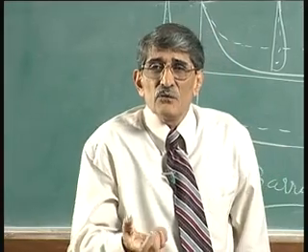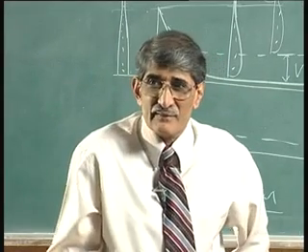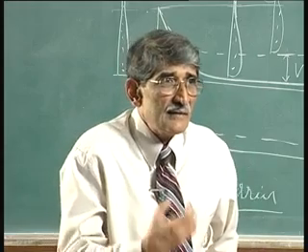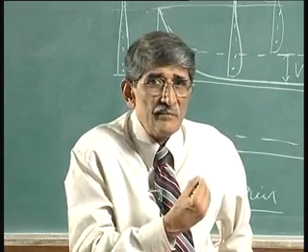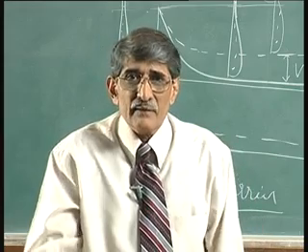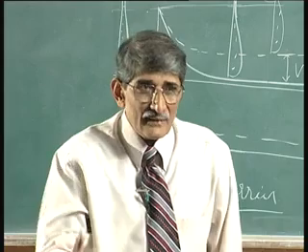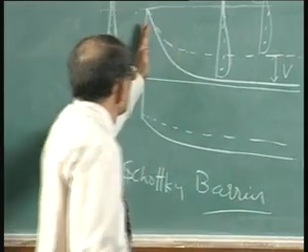So you have that number much smaller than the equilibrium concentration. If you have 10 to the power 16 as the equilibrium concentration, the crossing number is much smaller, maybe 10 to the 11, 10 to the 10. So, it is like putting a drop of water into the ocean, it disappears immediately. In the sense, it is not disturbing the thermal equilibrium here.